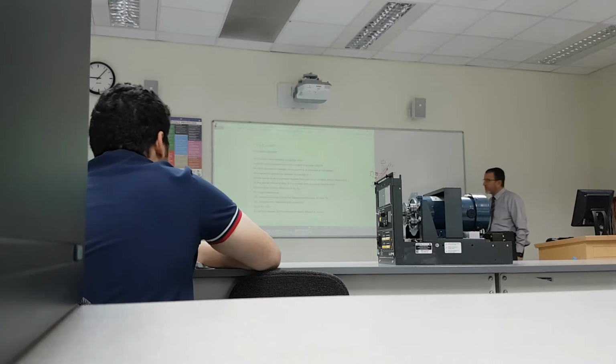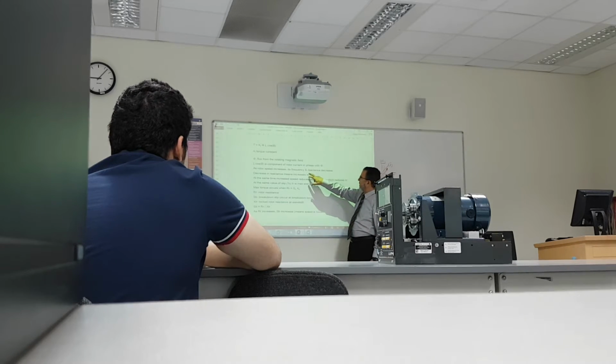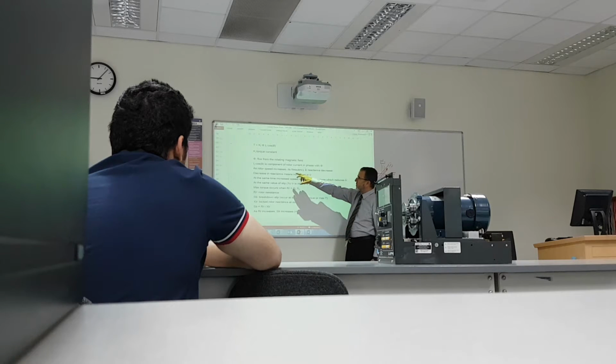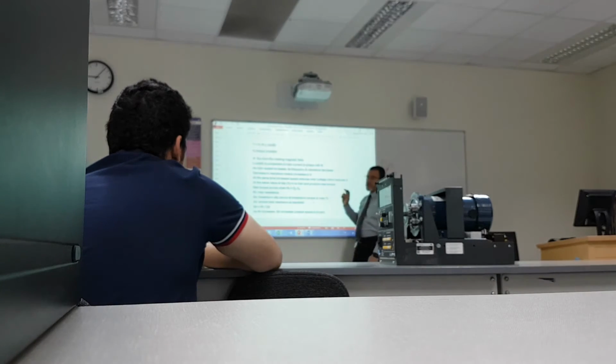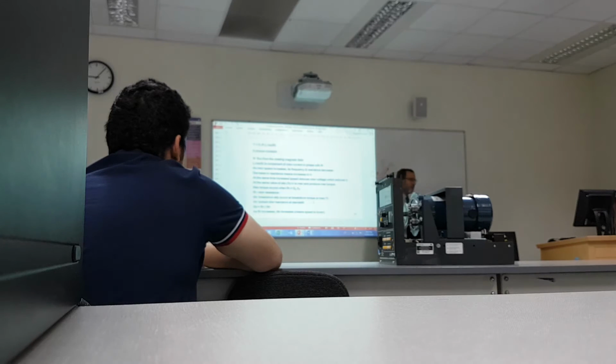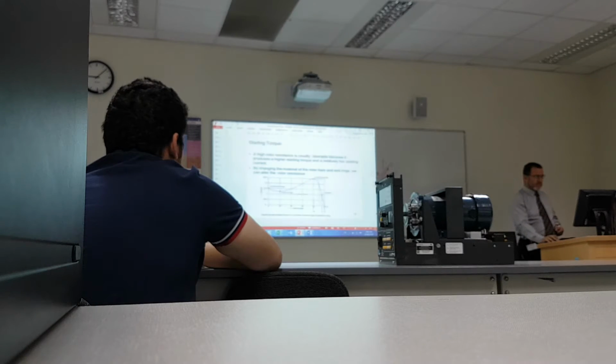Well, by the way, we had a discussion about this. Remember we thought these were contradicting? Here it says, as the rotor speed increases, its frequency and reactance decrease. This means an increase in current. Here it says it reduces current. There are actually competing forces in the operation of the motor. That's why you get this kind of graph.